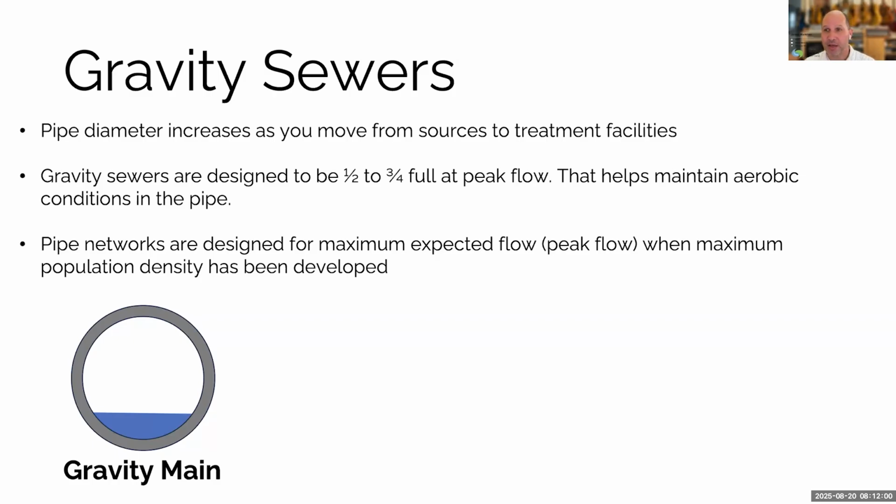So when you're thinking about the design piece, the maximum flow is going to vary from location to location. Here in New Mexico, for example, there's a marked difference between typical flows in rural areas versus urban areas. Out in the country, it's typically about 60 gallons per day per person, whereas in urban areas, for some reason, it's about 125. I guess city folks are more wasteful. But when that flow happens is pretty universal.